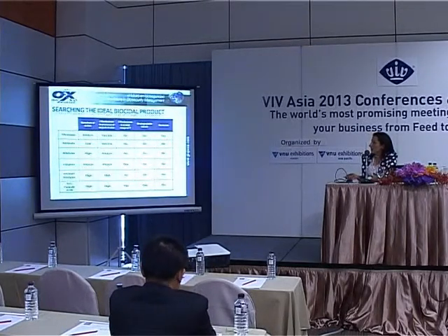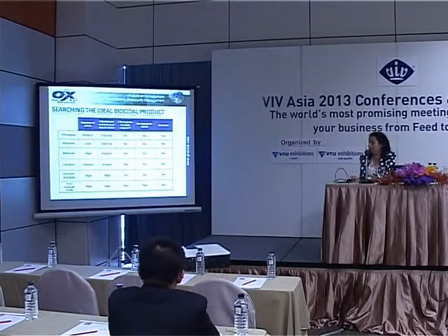Also, biodegradable nature is only fulfilled by hydrogen peroxide and peracetic acid. And these ones, at a diluted rate, are non-corrosive. The only disinfectants that are corrosive are the chlorinated anyway. But complying with all these features, we only have one possible combination, which will be the mixture of hydrogen peroxide and peracetic acid.